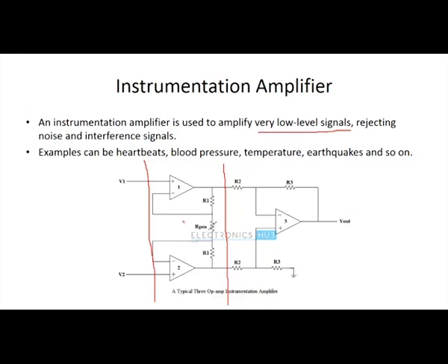So you have to split the module and calculate the output voltages according to the input voltages assumed to be given. The upper amplifier is considered as A1. So for A1 there are two input voltages V1 and V2. So only for A1, if you redraw the circuit, only the A1 circuit will be redrawn here.